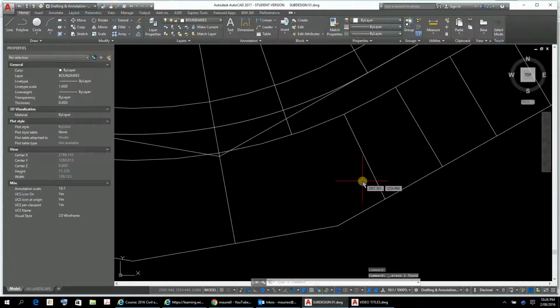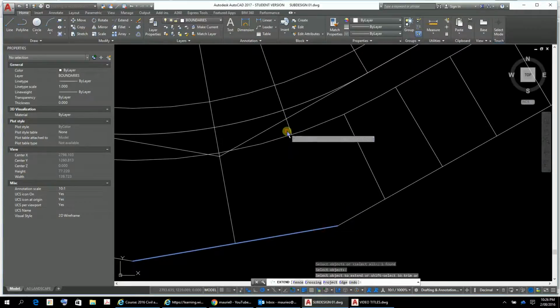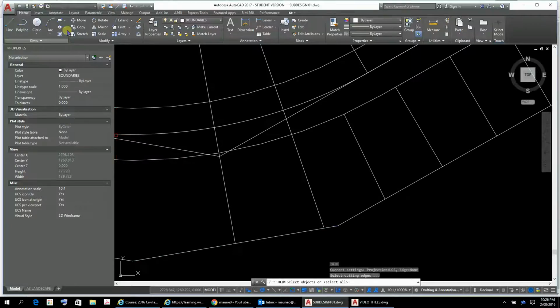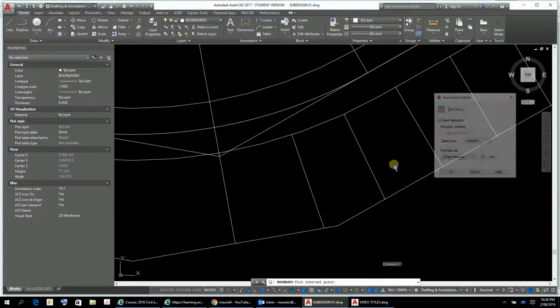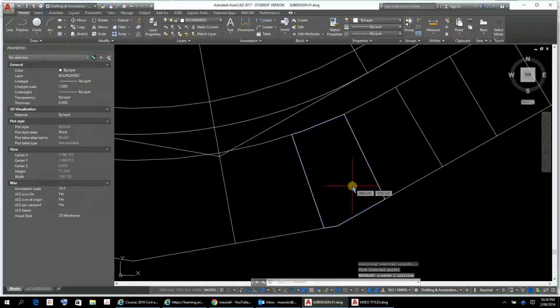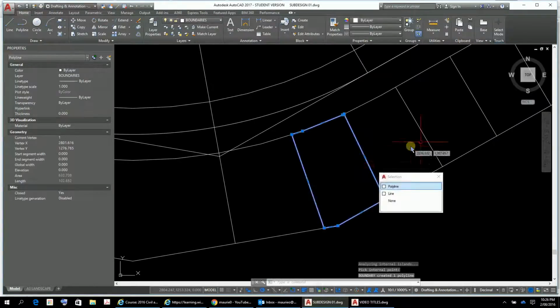Delete, and extend again, pretty similar, extend through to there, finish my selection with it there. Okay, I'm going to trim that to that line there, like so, and cut that through there. Do my boundary, which will give me my area, enter, I'll hit on that. Okay, now what I've got there is an area of 632. I'm going to leave that at 632.